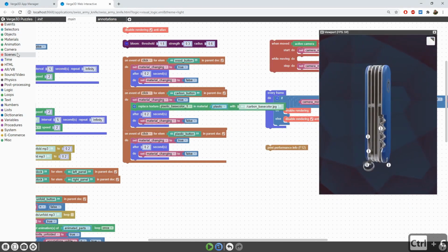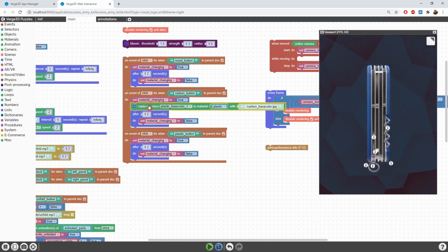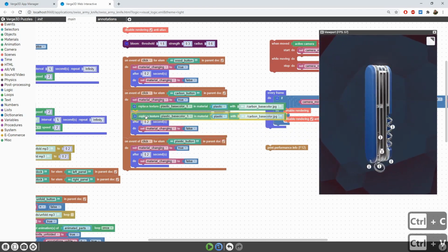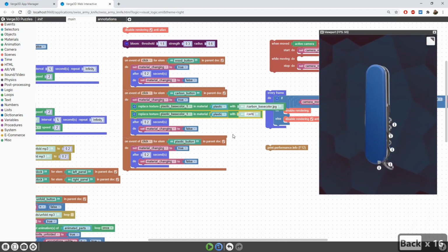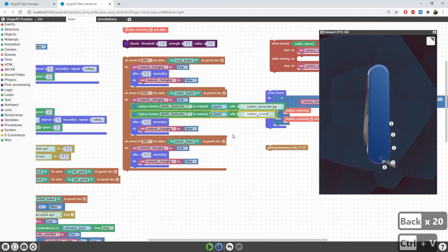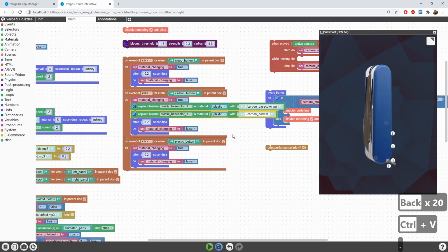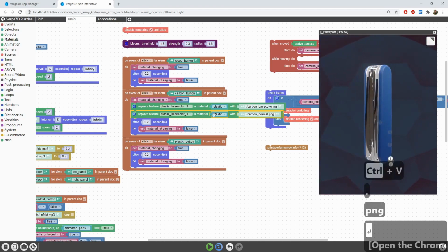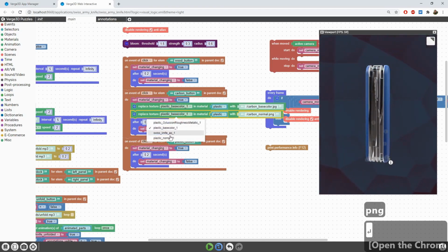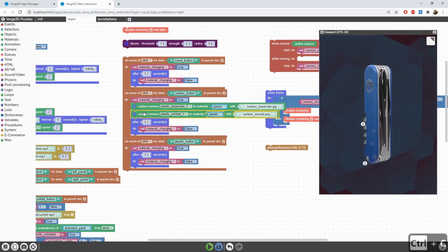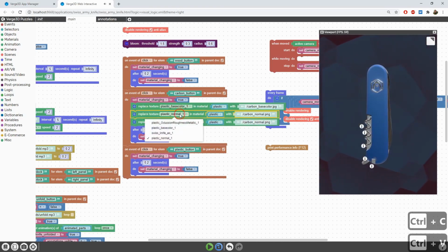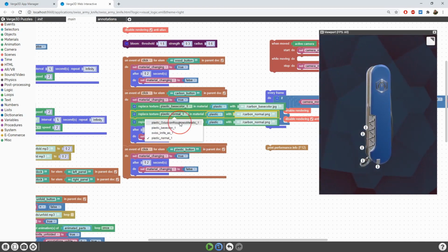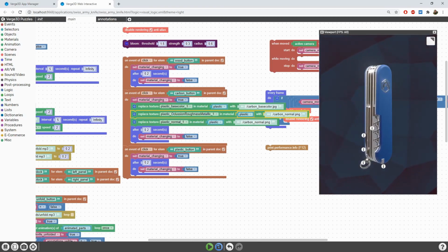Next texture we'll handle is the normal map. Let's copy and paste this puzzle. Paste the file name for the normal map. In this case, this is a PNG file. Be sure to switch the texture slot to plastic normal. Finally, let's duplicate these puzzles once again and switch it to Occlusion-Roughness-Metallic. Let's copy the file name.